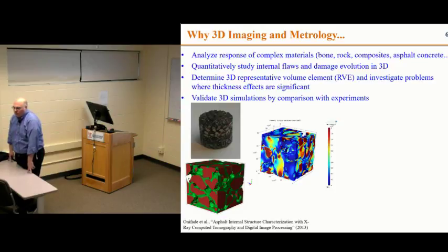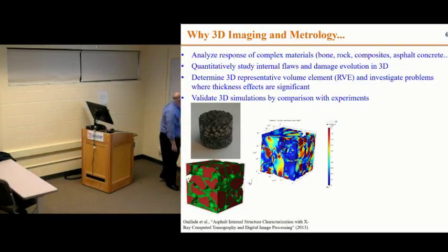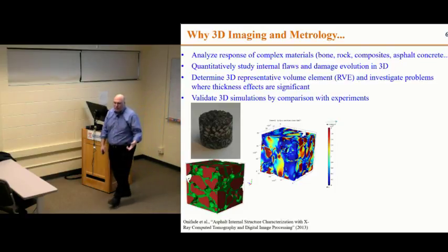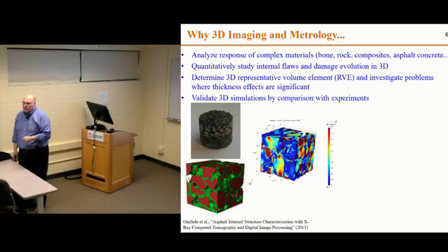What do you think about challenges other than just getting the images? I think DVC is a problem. The more of these you add in there, the more of the hard particles you put, the more difficult it is to do strain measurements if the only place you can measure strain is in the matrix, which is where the dots, the markers, are. That's the biggest challenge for me. So the higher the volume fraction, the less likely we will be able to make quantitative measurements.